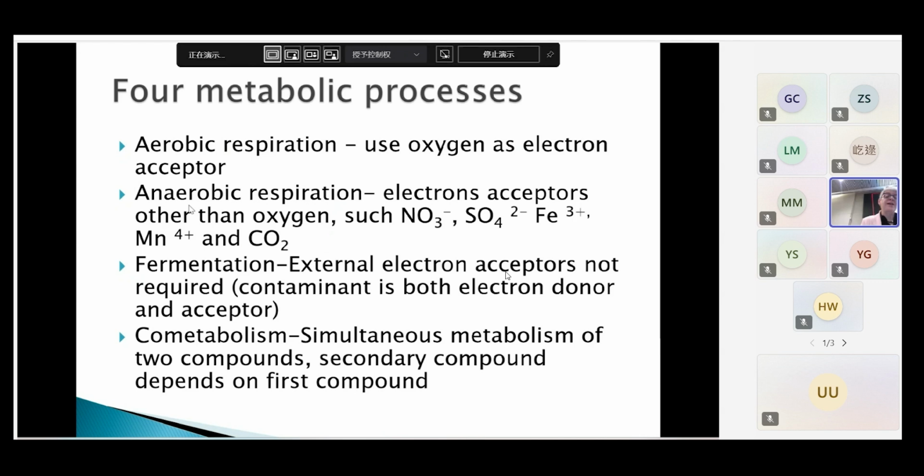So over 90 days, they added some nutrients, did some tilling three times a week, maintained the moisture content, and monitored the contaminants and the carbon dioxide and things like this. It took about 90 days to treat this soil, so definitely an ex situ type of remediation.